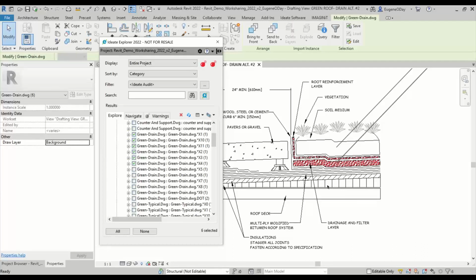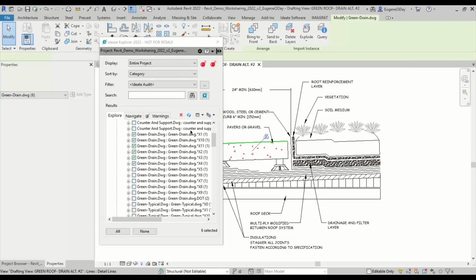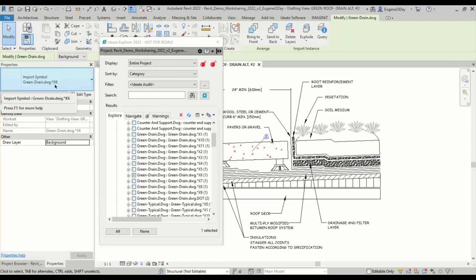And really what's happening is, if I look at this a little deeper and click onto that, that is a DWG file. It looks like maybe a dynamic block or detail that was brought in, and somebody just did a partial explode in Revit. So we still have some residual DWG files within there. At least they didn't do a full explode, but nonetheless, we've got some details here that we've got to clean up and do something with.